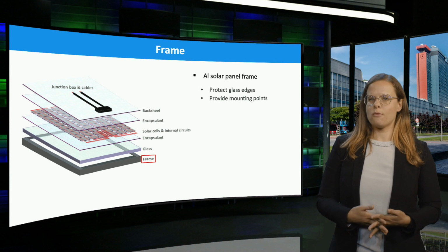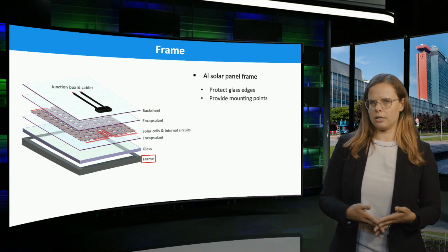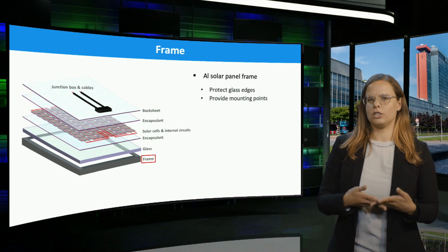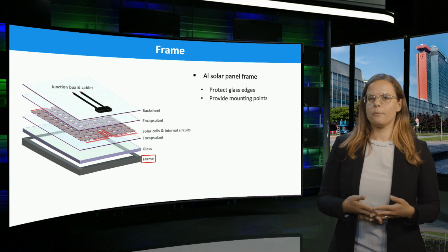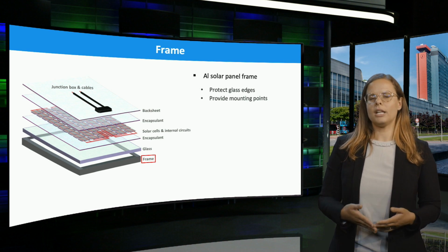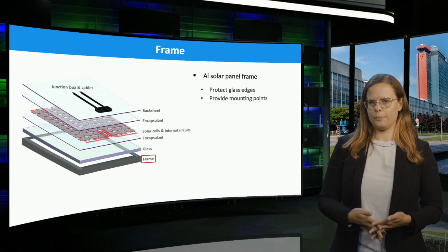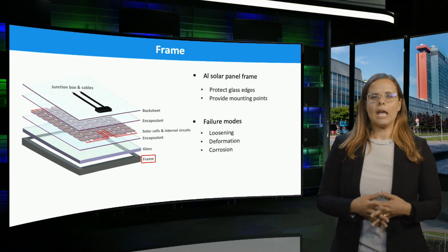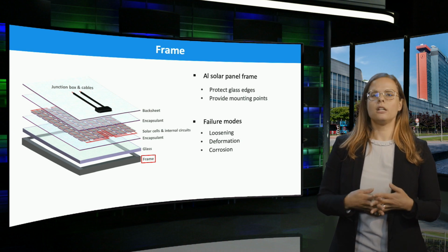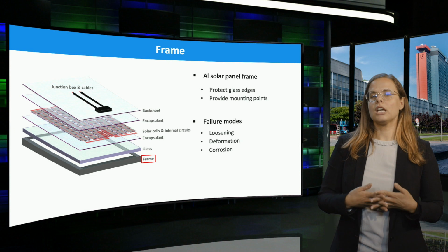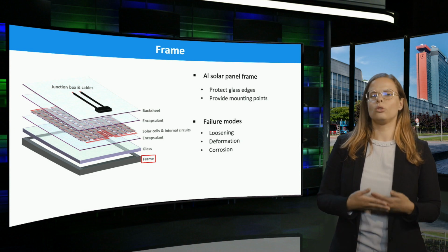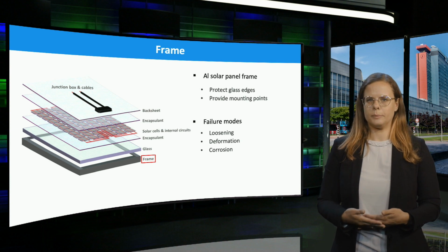Besides, the aluminum frame has good conductive properties and can be used as lightning protection during thunderstorms. Moreover, the strength of the aluminum frame is high, which could provide a stable and reliable support to the module. However, in practical use, frames can become loosened, deformed, and corroded over time. This increases the risk of module damage and in turn can contribute to degradation of the module performance.